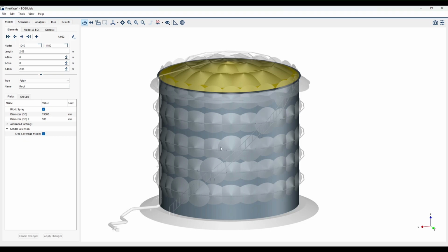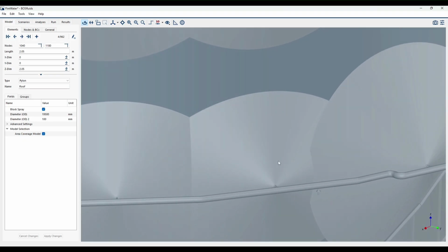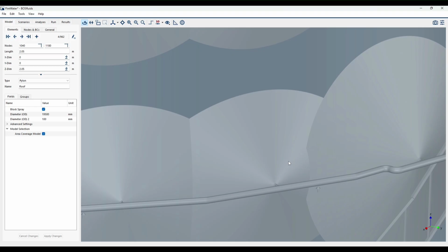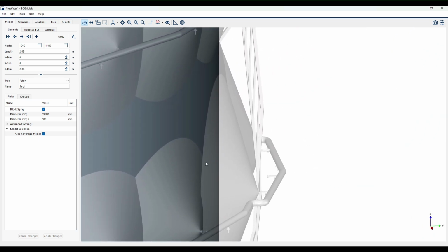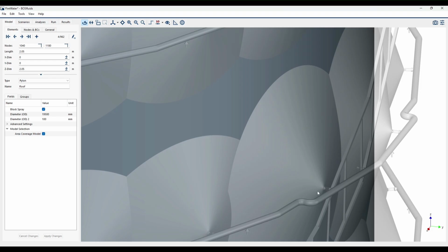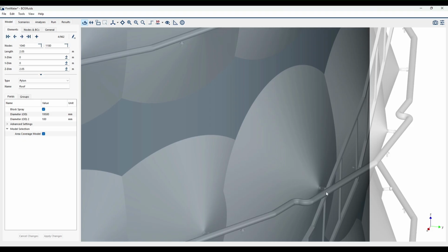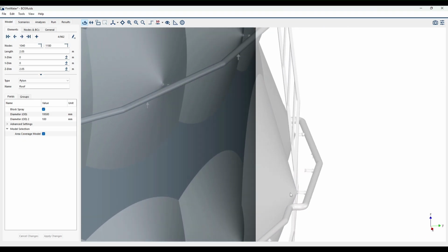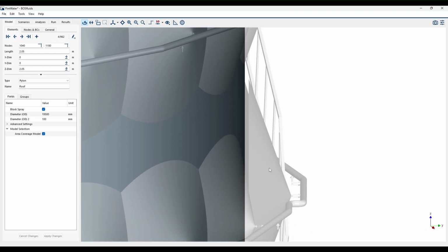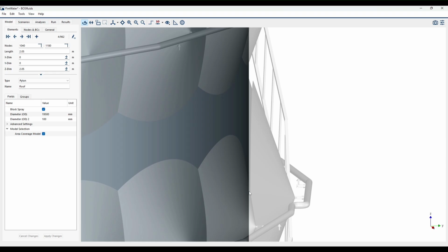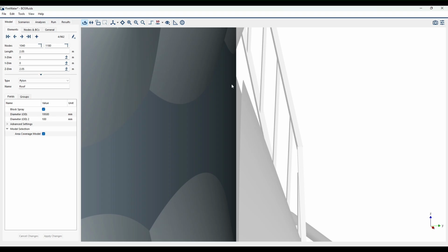So now something else we can do is to turn on the spray profiles. This is quite useful because then we can see if with this distance of 0.7 all the sprinklers are touching the surface. In this case we can see that they are. But if we go here to the stairs, we can see that we have a loop just to avoid the stairs, and that increases the distance. And when we check in detail what's going on here, we can see that the distance is larger than 0.7, and that's why the profile doesn't touch the surface.